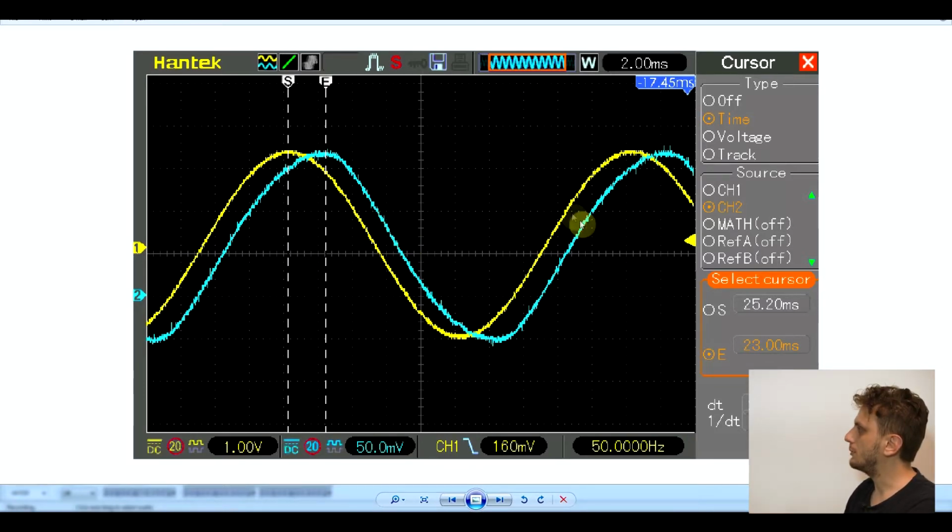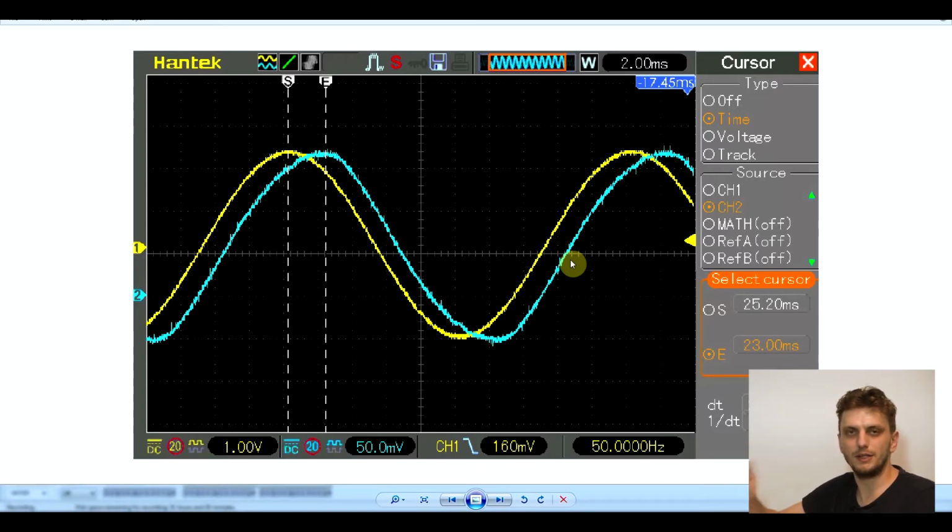We see the same phenomenon happening on both sides. We have a negative voltage and positive current, and we have positive voltage and negative current. That means that part of the energy that we consume from the generator, we're putting back in. So it's not really being wasted, but all this power needs to travel along the lines. Power factor actually refers to how much of the power that traveled along the line actually gets used up as useful power. All of this power that just gets stored and then put back in is not really useful. The useful power is only the power that we're taking out from the system.